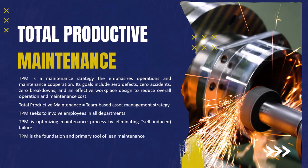We learned in our last video about the birth of total productive maintenance and how it is based on the operator-based maintenance concept. So total productive maintenance is a strategy that focuses on the operation and maintenance cooperation, and it aims for zero defects, zero accidents, and zero breakdowns. This is why it is even called the zero strategy sometimes. It aims for an effective workplace design to reduce any waste, which will reduce the overall operation and maintenance cost. So total productive maintenance is actually a team-based asset management strategy, and this is by involving all employees from all departments in the maintenance process.